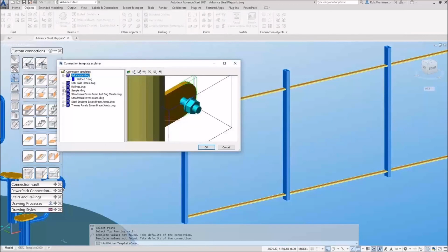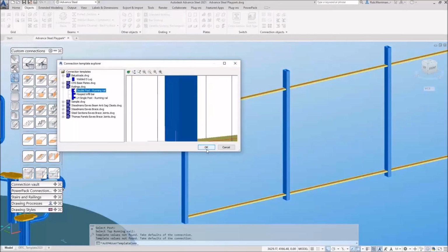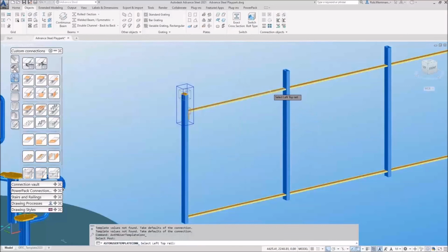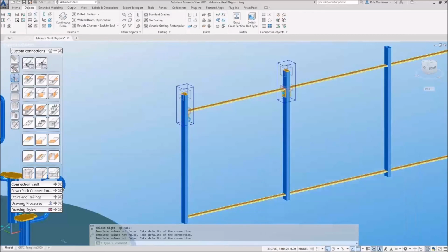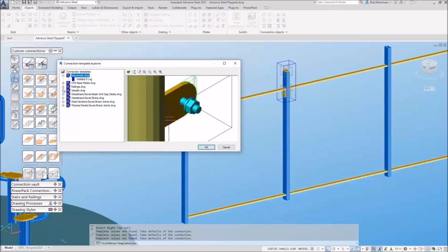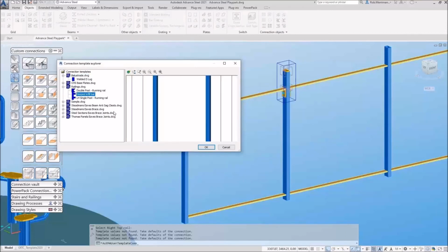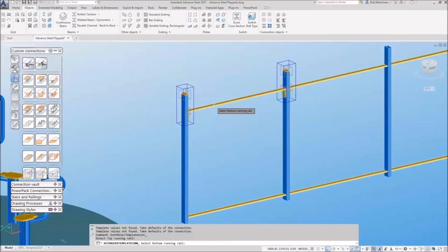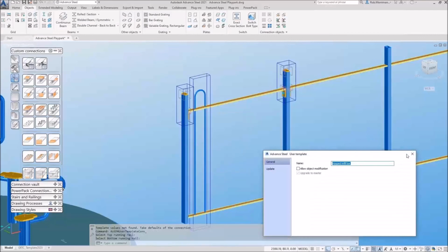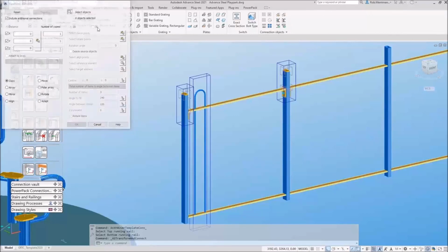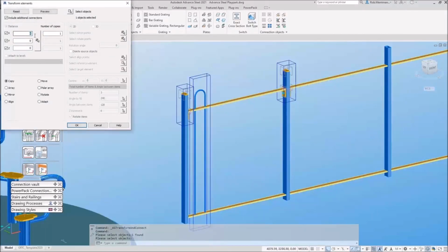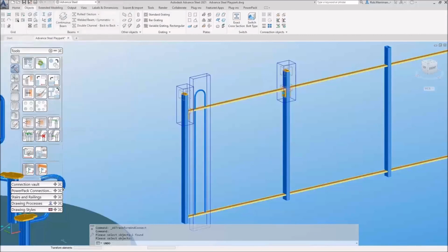For the other one, we can do the double post running rail. So select the post, select the left top rail, select the right top rail, and then hopefully with a little bit of luck we can then say hooped infill bar, top running rail, bottom running rail. That will put that in, and then we have something that we can say, right, we want to copy that 200 mil in the X direction, and we want, let's say 3, maybe 4. Do a preview on that.